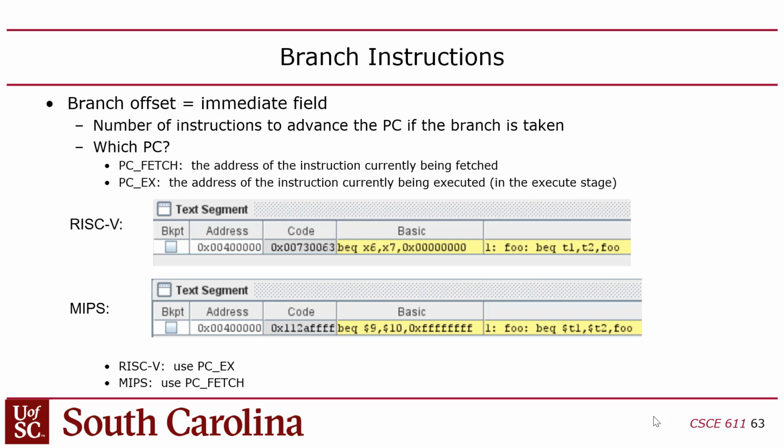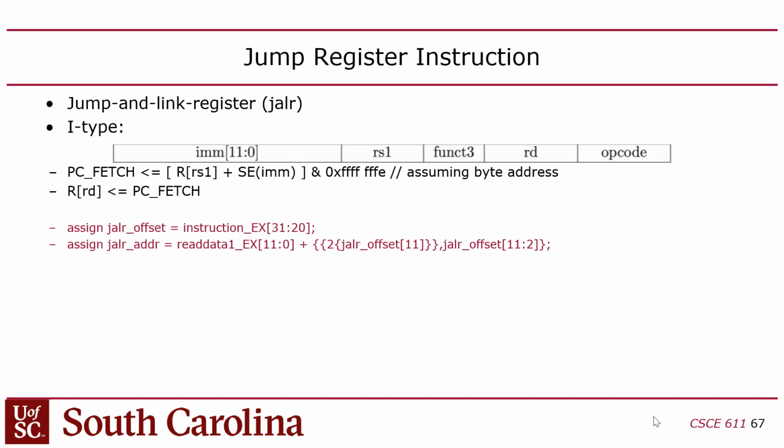If you remember, MIPS had a J-type instruction that had a pseudo direct address, whereas in RISC-V all the jumps are PC relative, including jump register. Do I remember that right? Jump register is kind of a direct address though, right? Because with jump register, you take the contents of the register and add the immediate. So you don't add the program counter.